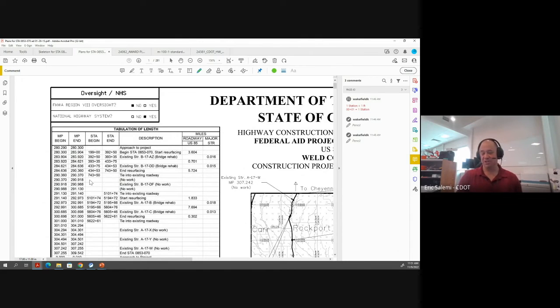Is it something where if they get to the milepost, they're going to see, which, Gene, I'm going to assume, you guys got to put in water quality ponds that will need to be maintained in the future. Well, once you get them to the location, they can clearly see what they need to do. So yeah, in that case, milepost would be sufficient, but Keith's exactly right. You got to be careful with milepost a little bit. If you need very accurate information, you do want to tie it to survey information, and we'll see some of the survey sheets here as we go through later.